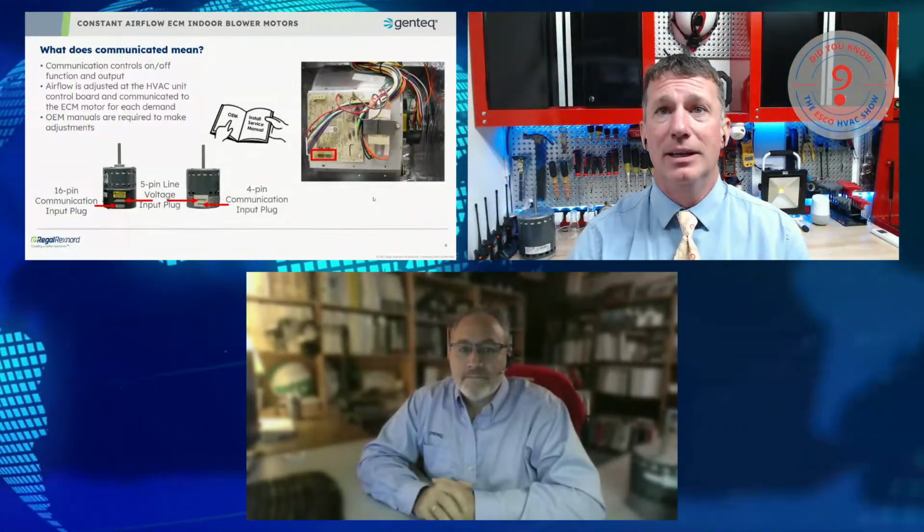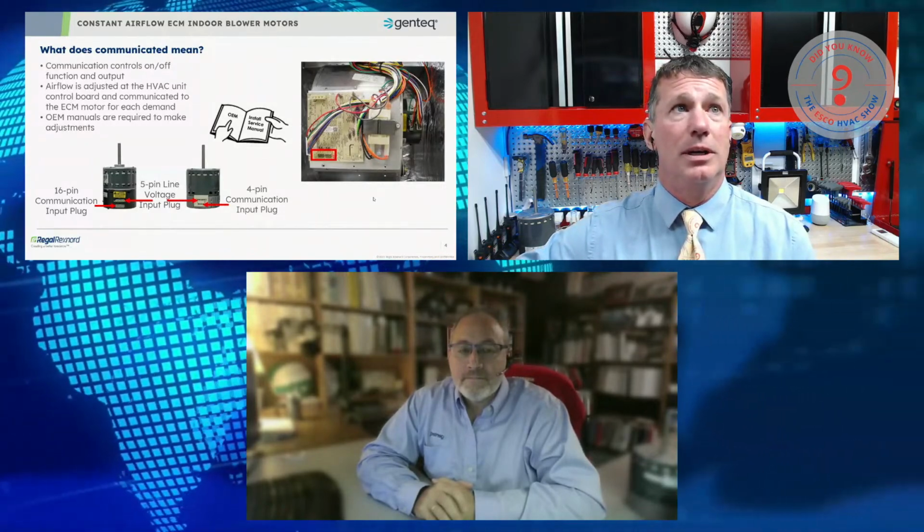So we're talking about metal oxide varistor. It is your surge protection that comes in off from our actual mod. And there was a time where that was a serviceable component. Those days have changed. We are now fully epoxied through the entire control, and so it has become a non-serviceable component. At least from my perspective. I don't know if the OEMs have a different perspective on that, but that is definitely where I ended up as a technician, was that those days of servicing are actually gone.